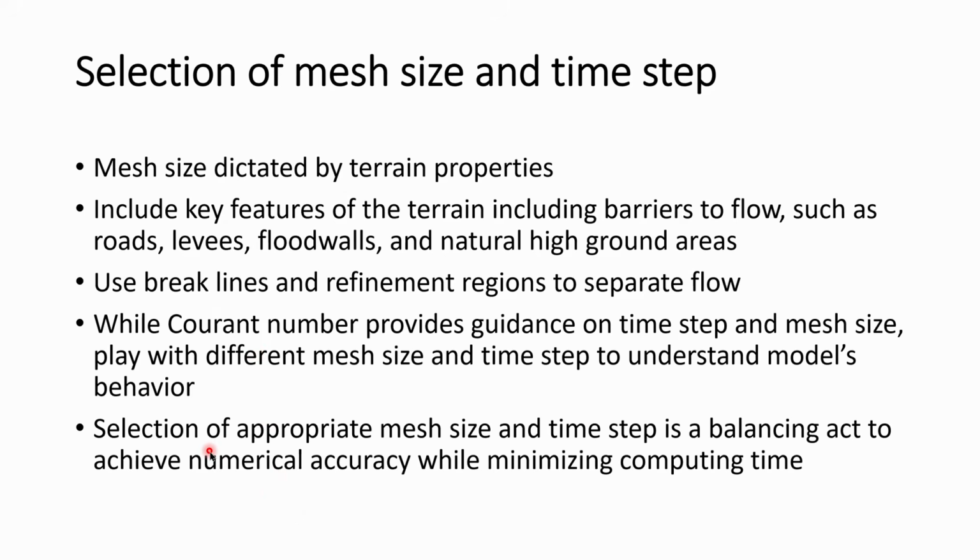So as I mentioned here as my last point, selection of appropriate mesh size and time step is a balancing act. So we have to make sure that we achieve numerical accuracy while also minimizing computing time, because you don't want to have very fine resolution and very small time step, because it will take very long for the simulation to complete. So again, as I said, you have to play around with the mesh size and the time step.